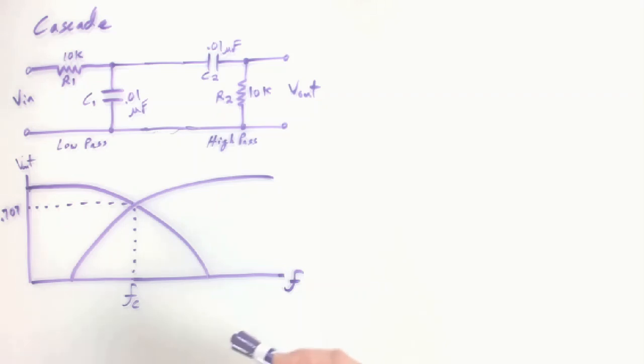I wanted to remind you that inductors, we haven't brought them into the mix, but you can do filter networks that use inductors, capacitors, resistors. Oftentimes you leave inductors out of the equation. They aren't as ideal. They have that winding resistance. They're heavy, they're bulky, take up space. But there are times where they come into the mix.